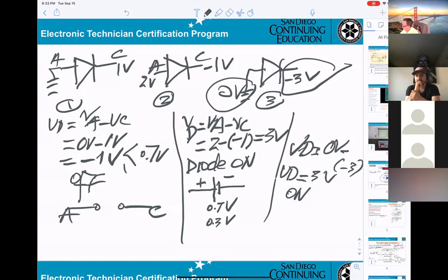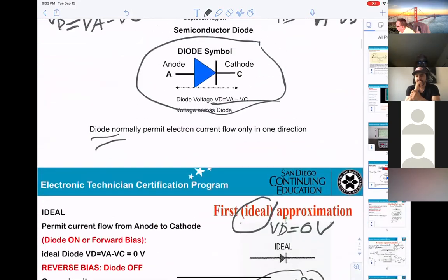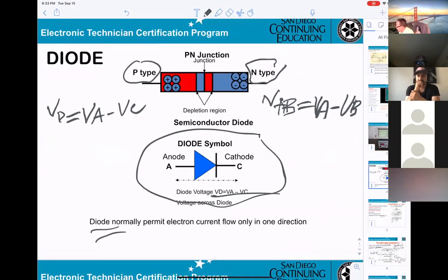They're telling you that's enough power for electrons to be moving. If you're less than 0.7, electrons can't move. If they're not moving, you don't have a current. It has to be at least 0.7 for silicon. For a different type, like germanium, they require 0.3. Okay?